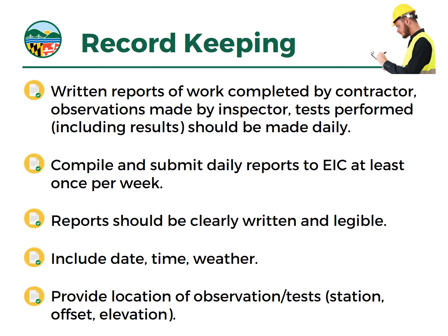Of course, we want to provide the location of observations and tests. We want to document that with some kind of benchmark for the site, whether that be stationing with offsets and elevations. That way we know where the tests were made.